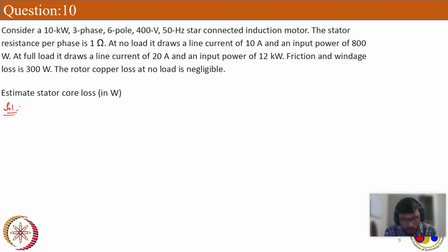Input power? No, they don't specify the input power like that. It's the net mechanical power available at the output. So whenever a manufacturer specifies the power in the nameplate details like this, the buyer or the consumer who buys the machine should know how much power is actually useful. So whatever power they give in the data is useful power only. If I'm going to buy a machine, I go and see the machine's nameplate details. There it is written as a 10 kilowatt machine. So okay, 10 kilowatt is my useful power. That's what I need. So here, 10 kilowatt is the useful power. That is the shaft power, or you can say the net mechanical power.